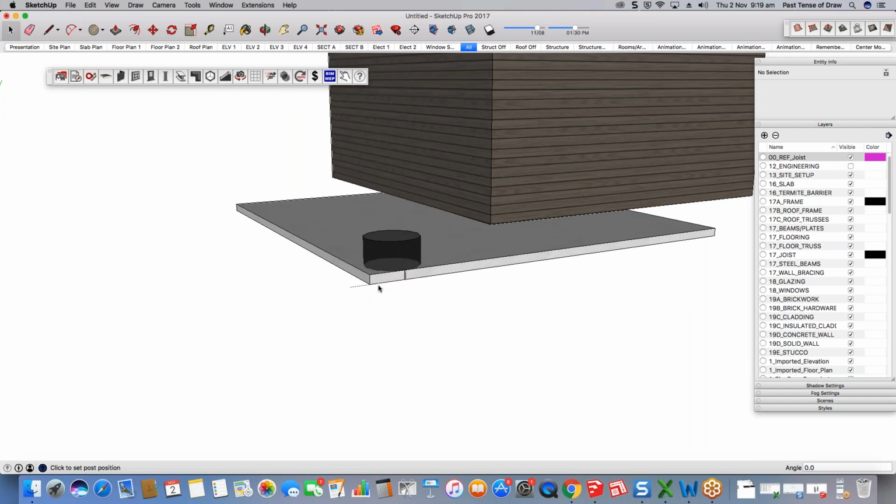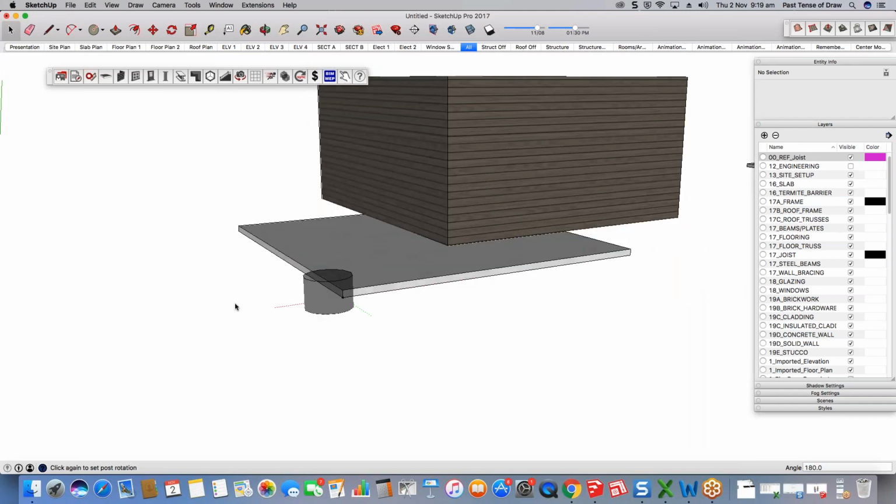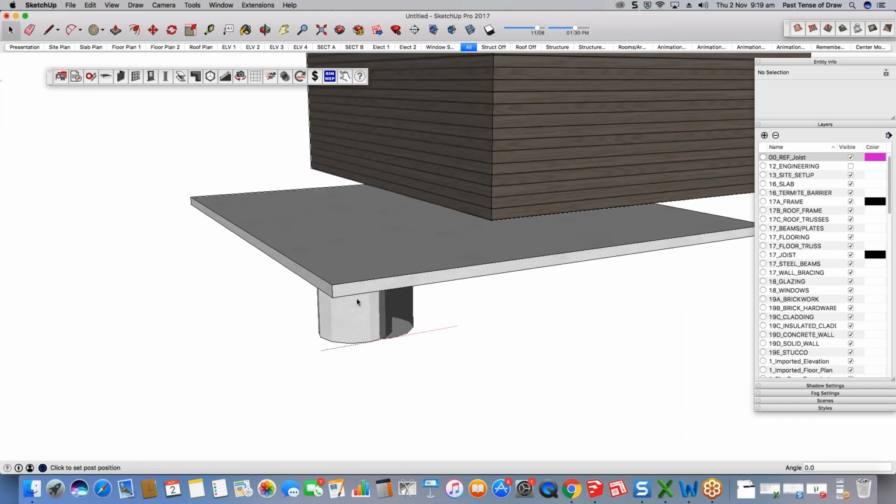When you're putting in these items, you want to left click to start. But as you'll see, it's not going in the direction that I want. So if you right click, or click on the right arrow on your keyboard, I should say, it's going to toggle through the different alignments, center points. But as you can see, if I keep on toggling, it goes underneath. So I can go above and change the position from where it's aligned and below. And then I simply left click to place it.